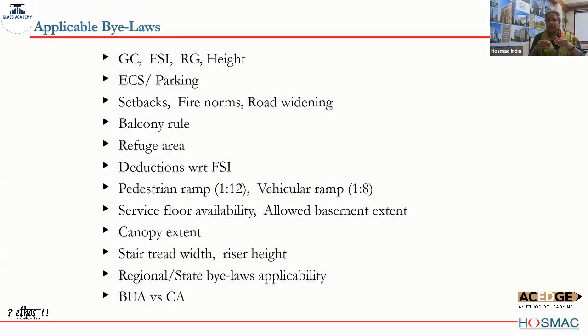What is able to be constructed. So all the frills and the extras are construction area, the one where the contractor is going to build and pay. And what the client is going to build is built up area. Also, the basement, if it is used for services, it's free of built up area. It's free of FSI. So construction area will be counted, but not in built up area.